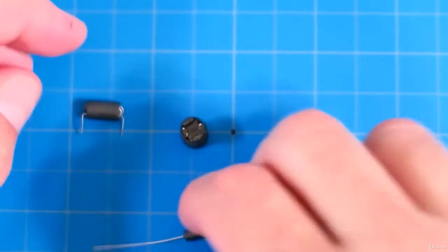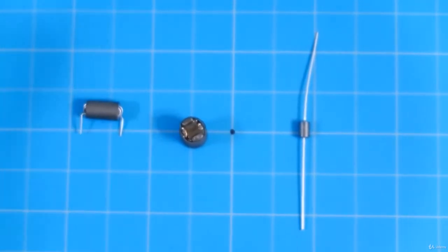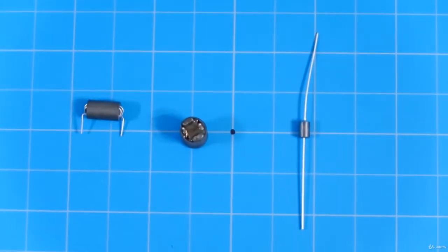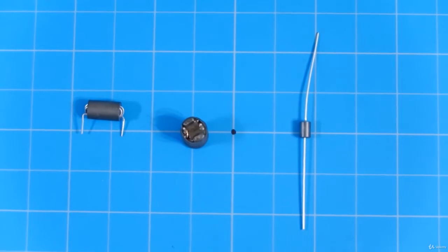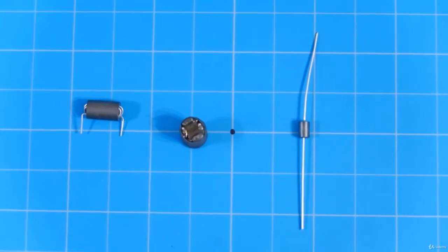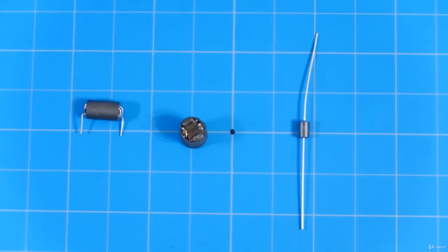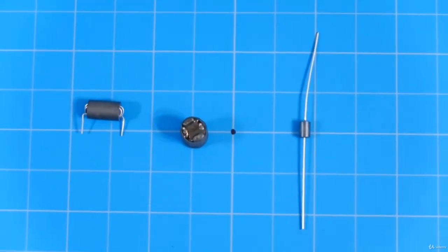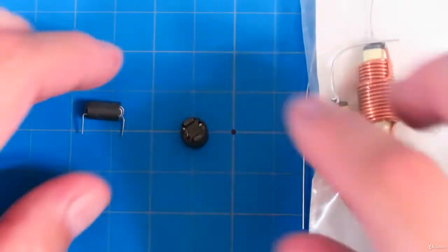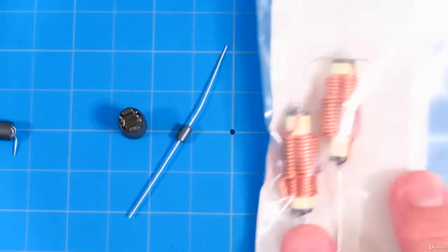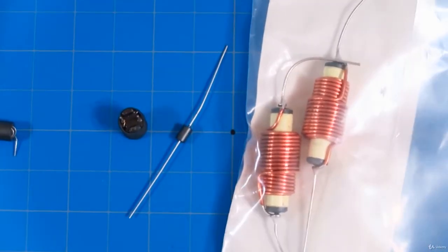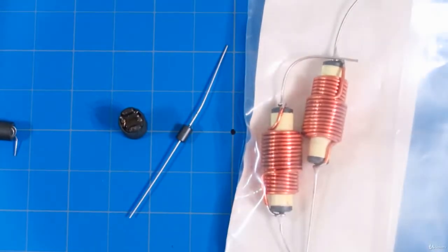Okay, so let's come back to our inductors here, since they have the floor. All inductors are coils of wire. You take wire, you coil it up, and you've got an inductor. If you wrap it around something that has magnetic properties like iron or ferrite, then it'll have more inductance. We've got 3 of them right here, and let me show you what's going on inside. Here's another inductor, and inside of this is actually ferrite.